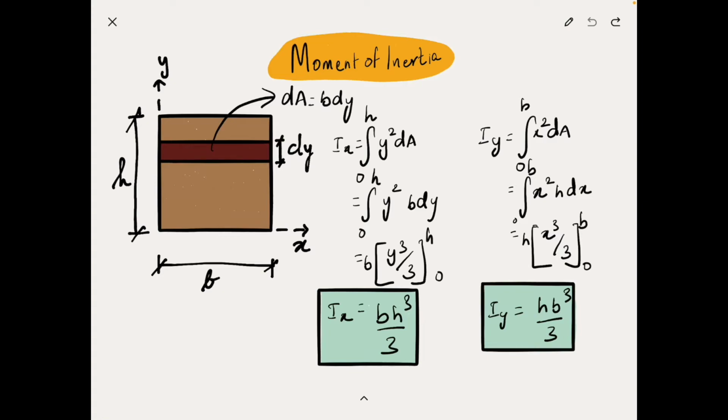When calculating moment of inertia, it is very important to consider the influence of the reference axis of the deformation or bending. For more complex sections such as T or I, it is possible that the bending axis is not passing exactly at the centroid of the cross section. So for such a case, we need to be in a position to calculate the moment of inertia with respect to any reference axis away from the centroid. Moment of inertia along the centroid axis for usual cross sections such as circular, triangular or others are very much available in textbooks and internet. But to calculate the moment of inertia for any given axis, we can make use of the parallel axis theorem. In the next section, we will discuss the parallel axis theorem with an example.